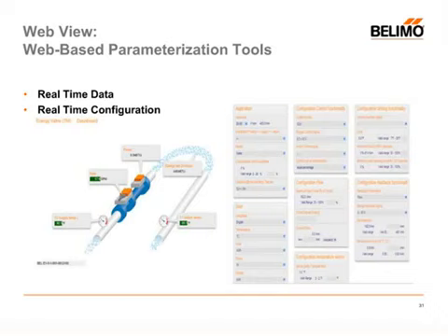Also, while viewing this data, you can make changes. You can change your flow settings. You can increase or decrease your flow. You can change it from pressure dependent to pressure independent mode, for example. You can change your delta T set point. If you want to change your delta T from 12 to 14 because you realize that by having the delta T manager on, you're able to optimize your coil, you can do that. All this can be done in real time via the WebView. A very powerful tool that is integrated directly into the energy valve itself.